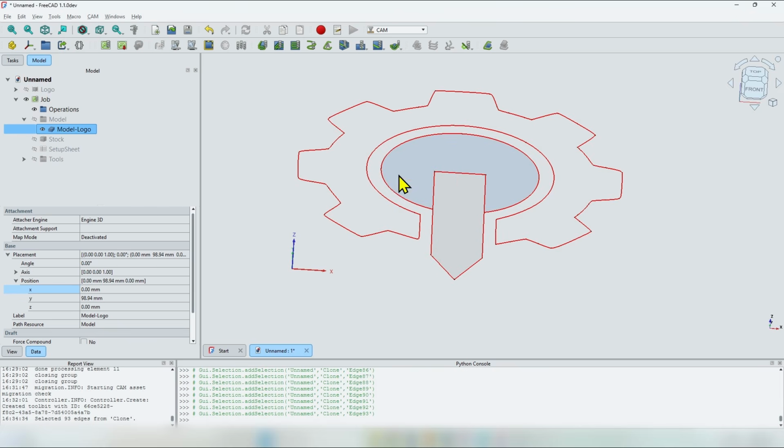and run the Only Edges macro. This will select all the edges of the object that is selected. If you need this macro, you will find the link to it in the description of the video. There you can download it for free or together with a small donation.